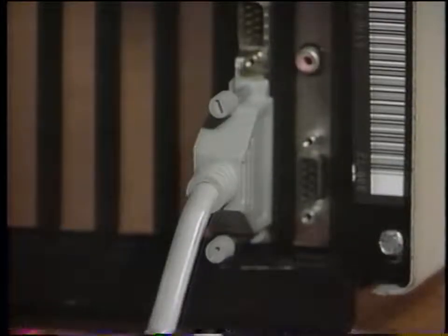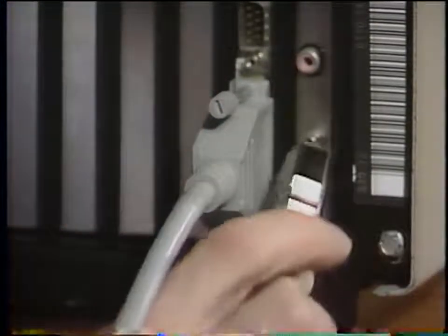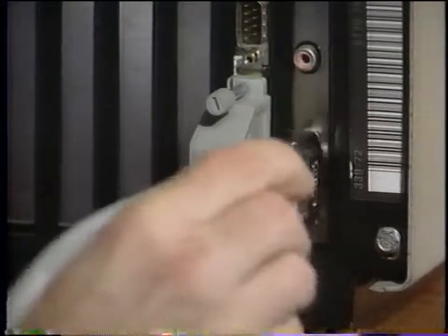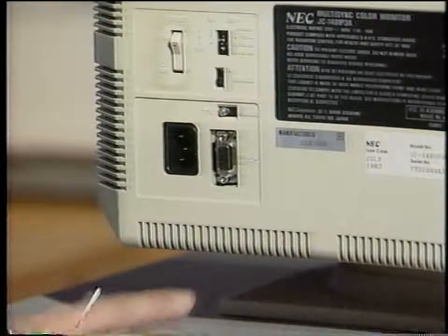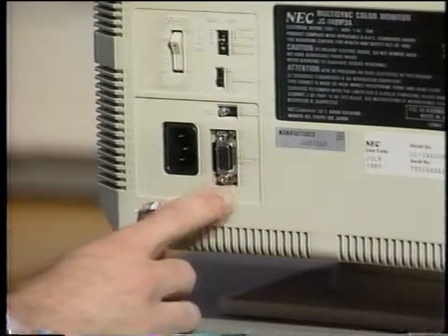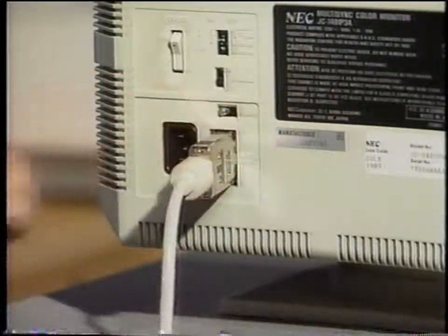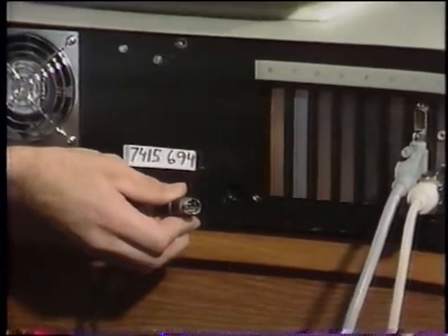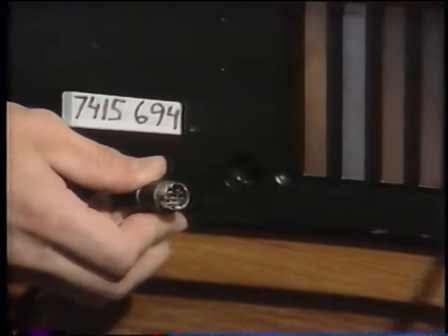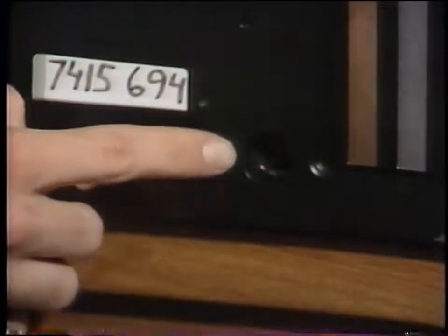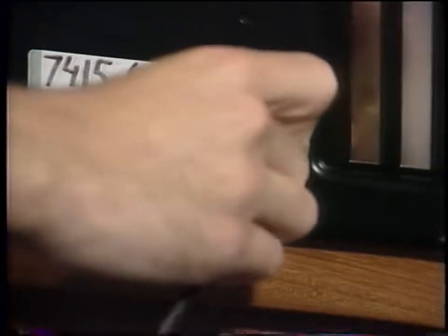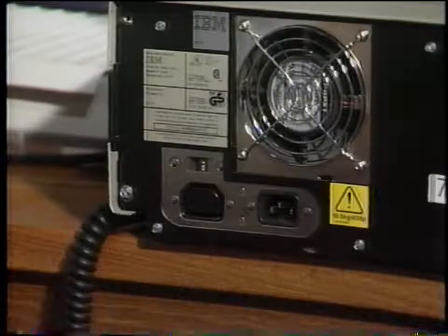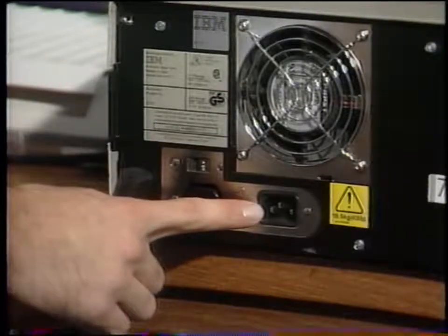Connect the monitor cable to the connector on the computer and tighten the screws. Or push the connector into the hole if you have a composite monitor. If the monitor cable is not already connected to the monitor itself, connect the other end of the cable to the monitor. Now connect the keyboard to the system unit. The connector for the keyboard is a round female plug to which only the keyboard will connect. In most cases, it is in the middle rear of the system unit, but it may also be on the front.